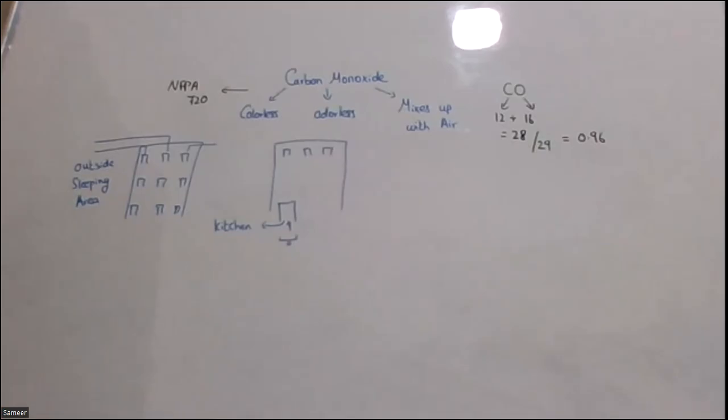What are the actions that one should take whenever carbon monoxide is detected? The first appropriate action is, because carbon monoxide tends to remove oxygen, you have to make sure that the carbon monoxide concentration is diluted, because the more concentration, the less oxygen available. You have to make sure that oxygen availability is up to a point where the occupants can continue breathing.